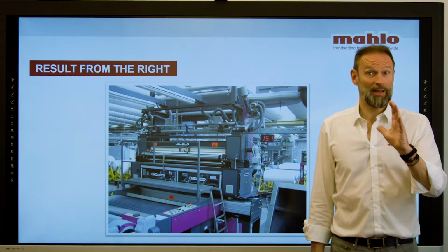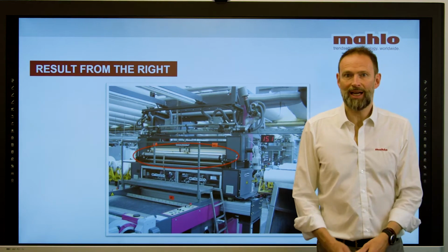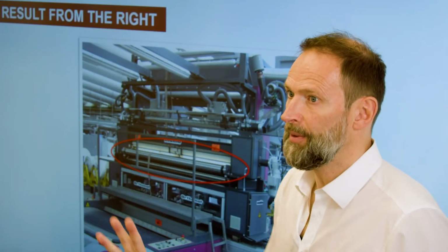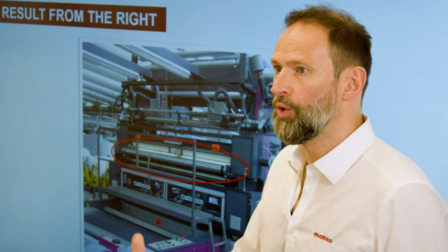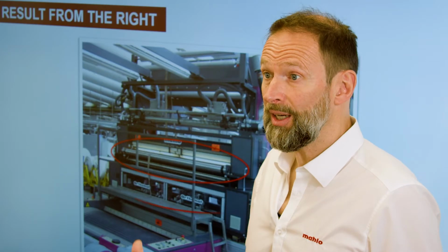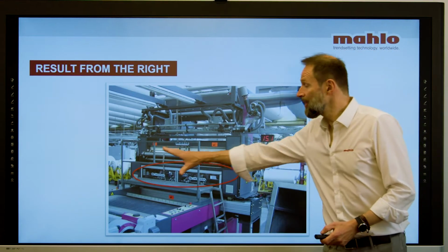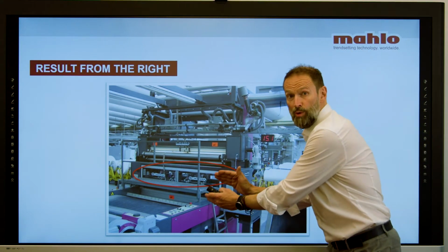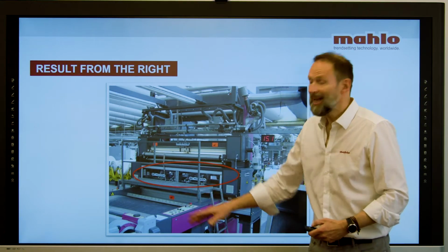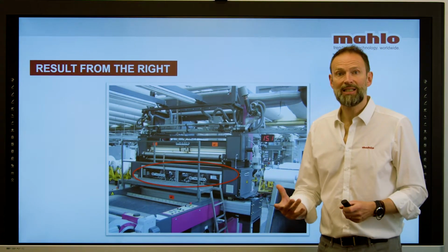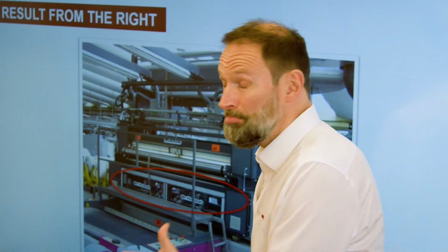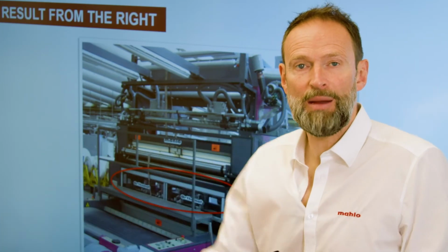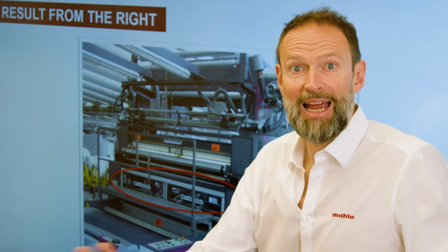Here you can see the installation from another perspective, and still you see the segment guiding roller on top of it to make sure that the fabric is guided very gently to the top of the entry. Then the main subject is the weft straightener, and from this position you can see even better how small the distance between the weft straightener and the printing table is, and we are really talking about just centimeters between the alignment of the fabric, the 100% straight fabric, and the printing table.